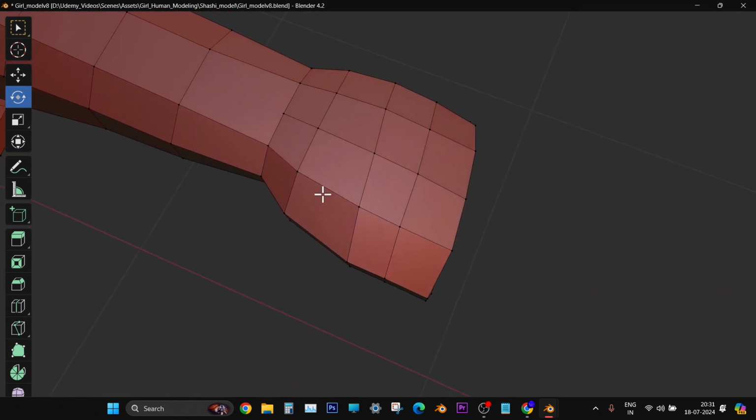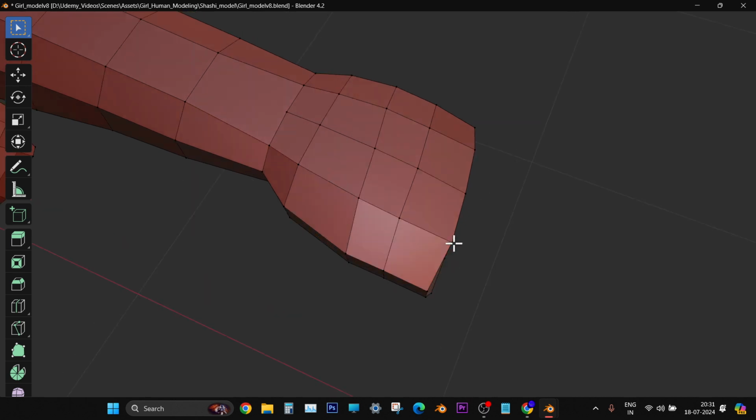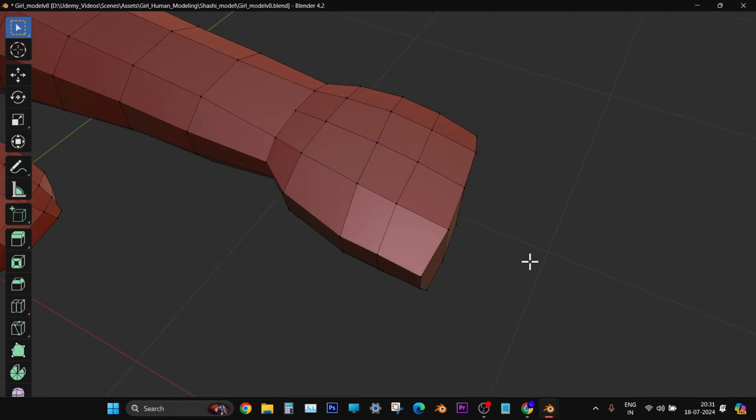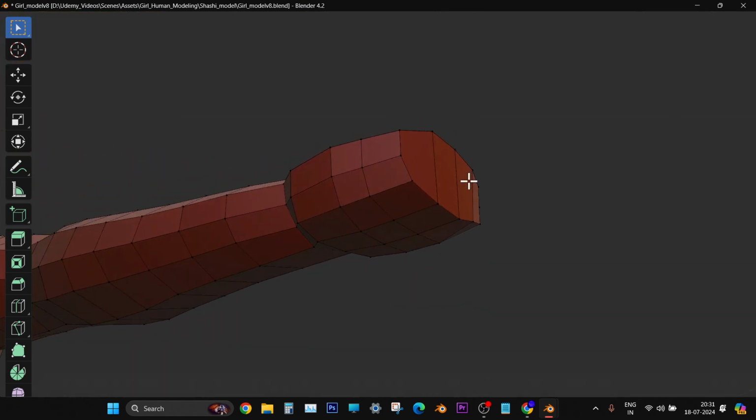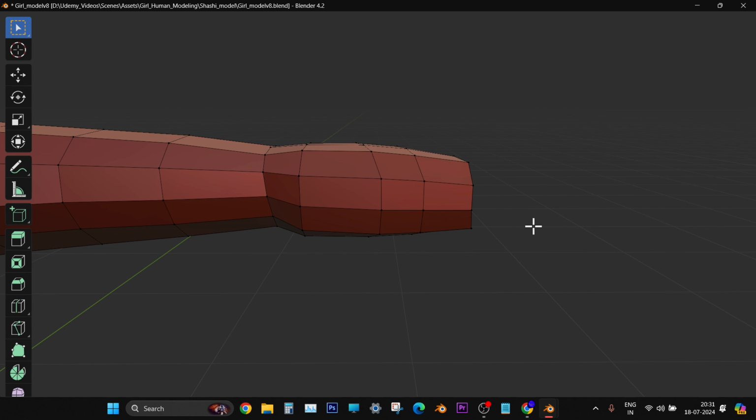So that we don't have to suffer after we add subdivisions or multi-resolution or anything, or make further shapes. In the beginning itself, whatever shape we have already done, we are reworking on the same shape again and again, just examining whether this shape, to whatever extent the vertices I have moved and placed, is correct or not, and whether I should do anything more.